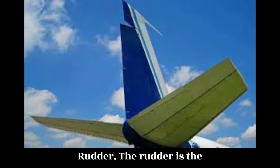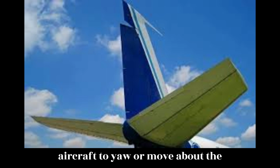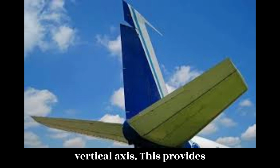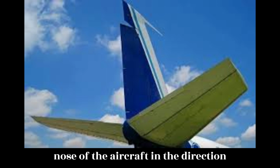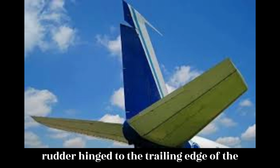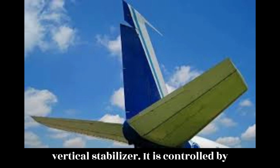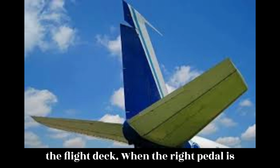Rudder. The rudder is the primary control surface that causes an aircraft to yaw or move about the vertical axis. This provides directional control and thus points the nose of the aircraft in the direction desired. Most aircraft have a single rudder hinged to the trailing edge of the vertical stabilizer. It is controlled by a pair of foot-operated rudder pedals in the flight deck.